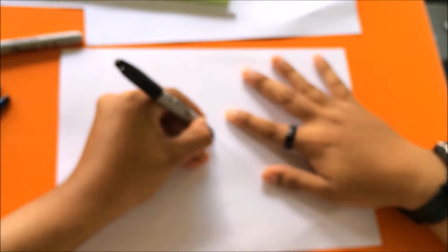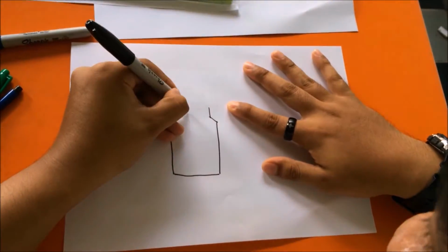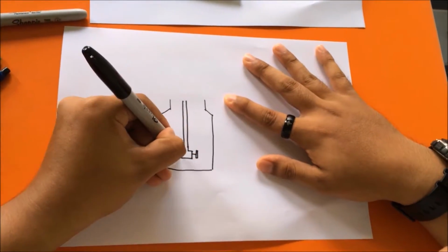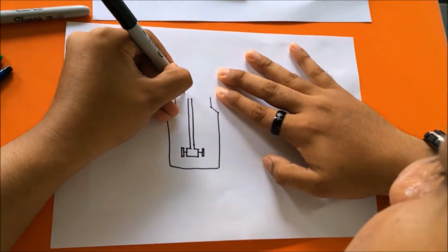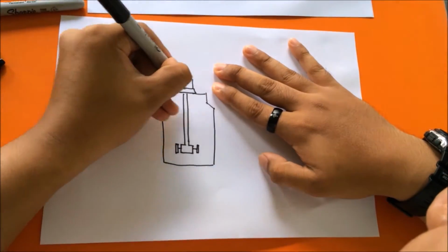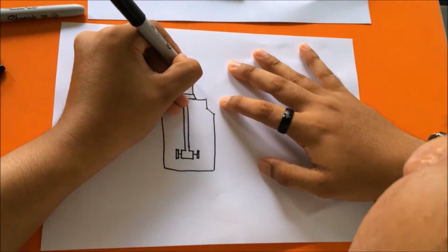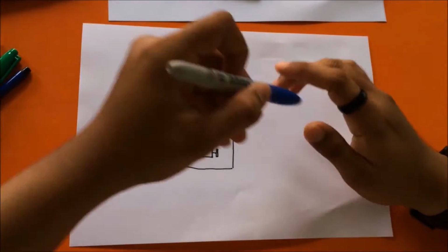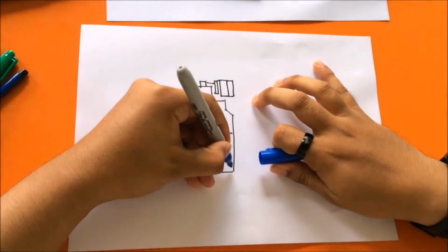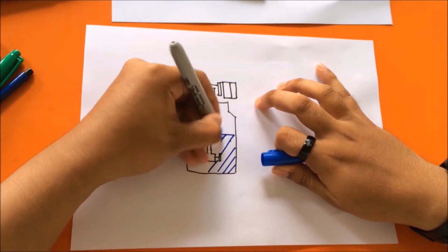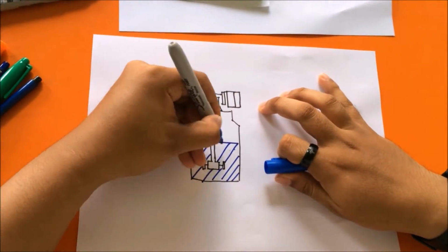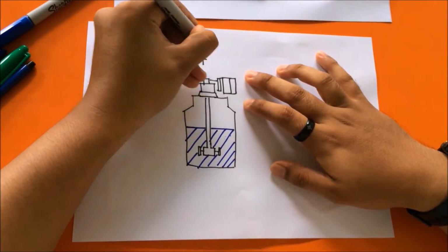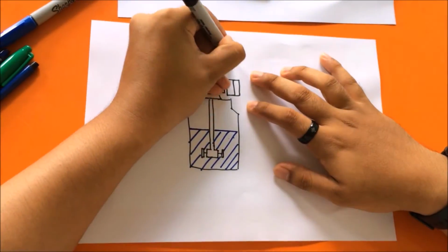Secondly, for agitator, in an agitated process, if the residue can solidify on cooling, then care should be taken to switch off agitation before solidification occurs to avoid breaking the agitator. Repeated heating of residues can lead to thermal instability due to thermal history. Maloperation upstream of the distillation, such as an overcharge of one of the components or an incomplete reaction, may affect the feed composition and consequently the thermal stability of the batch. Thermal stability screening can be carried out on materials doped with relevant materials of construction.